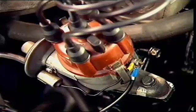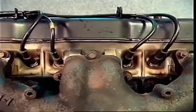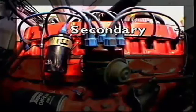a distributor, to house the contact breaker and distribute the high tension voltage from the ignition coil to the spark plugs to ignite the air-fuel mixture in each cylinder in the correct firing order; and connecting wires and leads suitable for conducting the current flowing in the system at the appropriate voltage level. When these components are connected together, they form two distinct circuits, primary and secondary.